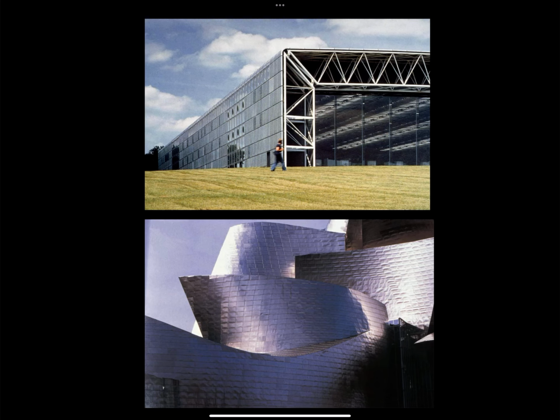The jointing systems are different. So the joints on the Sainsbury Centre are the neoprene gaskets. And this, as you remember, we discussed this as being a very innovative system. The joints on Bilbao are flat seam metal roof joints, in which the joint is made by interlocking or folding over layers of metal to join them together. This is a very traditional system, has been used for thousands of years, including on the Pantheon.